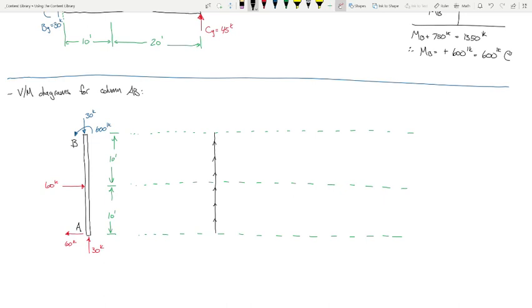And the reason it's doing that is because I'm assuming that as the analyst, when I was defining the joints, so when you define joints in a software program, it's basically X, Y, and Z of joint 1, X, Y, and Z of joint 2, X, Y, and Z of joint 3. You're entering in coordinates. And so the idea is that I would enter this coordinate first, then this one. And so when I define the member, I draw it from this joint to this one. And so that's going to define the direction in which it plots the shear and moment diagram. That's never really been a big problem for a beam, because from a software perspective, you would assume that you would just define it from left to right, which is the way we've been constructing them.